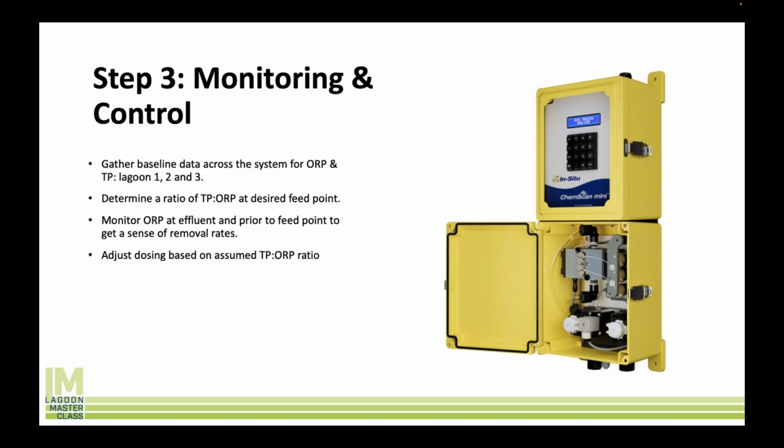Finally, you figured out your chemical, you figured out where you're going to feed it. I think monitoring is key, and dialing in your chemical dosing strategy is going to be important. So we highly recommend that you either get an analyzer like this, or you can get a handheld analyzer from Hach that will literally test the orthophosphate that you've got in the water, the soluble reactive form of phosphorus.